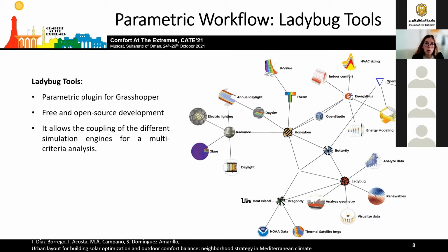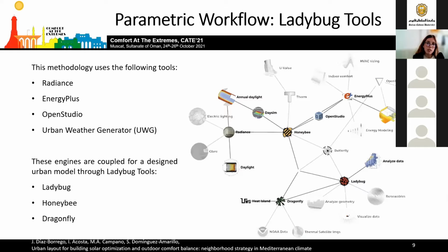Ladybug Tools is a family of components for environmental analysis in Grasshopper, in which simulation engines are coupled, allowing complex calculations to be done more efficiently in terms of computational costs. So we will use it to enhance the lighting efficiency of buildings in an urban fabric, as well as to establish design guidelines for cities from the study of climatic and morphological conditions at the neighborhood scale. For this research, only the following simulation programs have been used: Radiance, EnergyPlus, OpenStudio, and Urban Weather Generator, UWG, through Ladybug Tools using the Ladybug, Honeybee, and Dragonfly plugins.